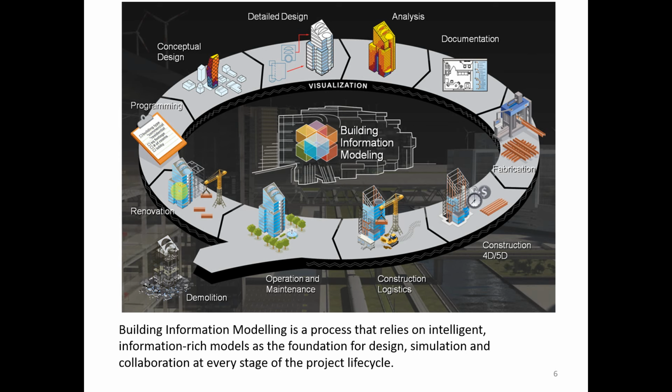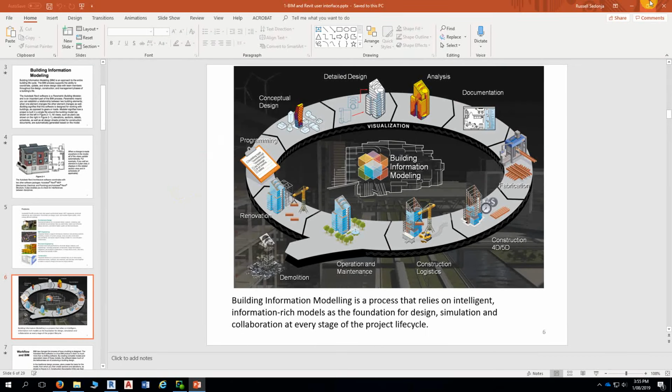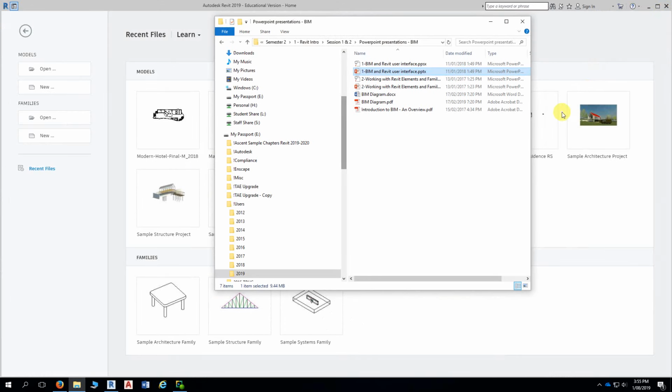Yeah, the thing is that if you have an AutoCAD 2D drawing and bring it into Revit, it will always only ever be 2D. It's the same problem you have with SketchUp. If you have a two-dimensional unit, it'll only ever be two-dimensional. I was wondering whether it can pick it up actually, because it has to be constructed. No, the third dimension has to be constructed around that.